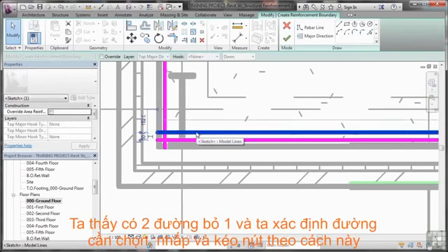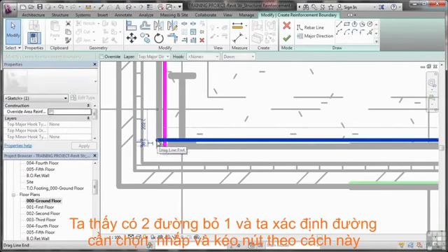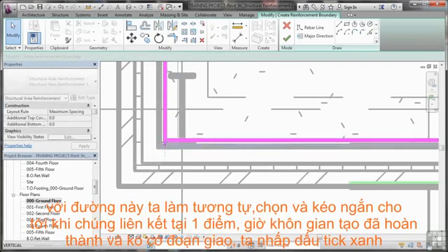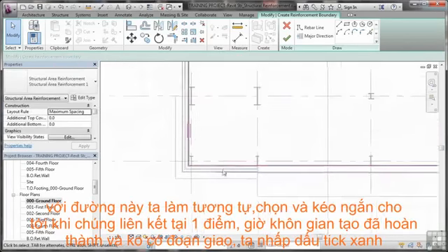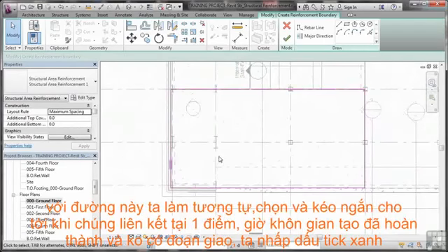That line there I don't actually need. It's these two lines here that I need to update. So again, click on the little drag line button, line it in that way, hit escape, click on this line, drag again. That now lines in nice and neatly. If I zoom out now, that should work fine because I've sorted out that intersection. But you cannot have intersections. It's got to be a closed loop.